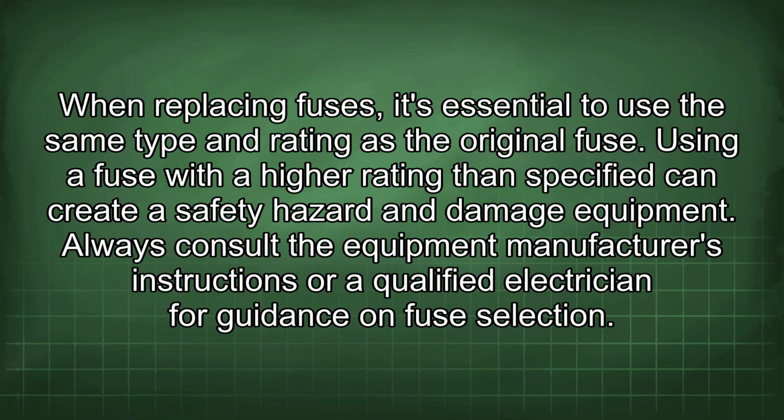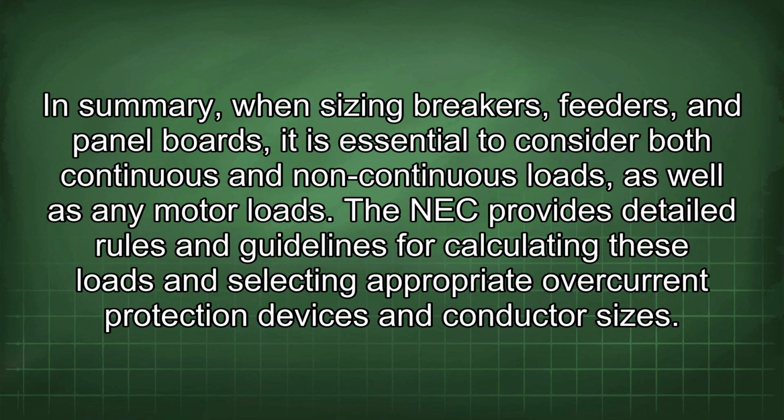Using a fuse with a higher rating than specified can create a safety hazard and damage equipment. Always consult the equipment manufacturer's instructions or a qualified electrician for guidance on fuse selection. In summary, when sizing breakers, feeders, and panel boards, it is essential to consider both continuous and non-continuous loads, as well as any motor loads. The NEC provides detailed rules and guidelines for calculating these loads and selecting appropriate overcurrent protection devices and conductor sizes.